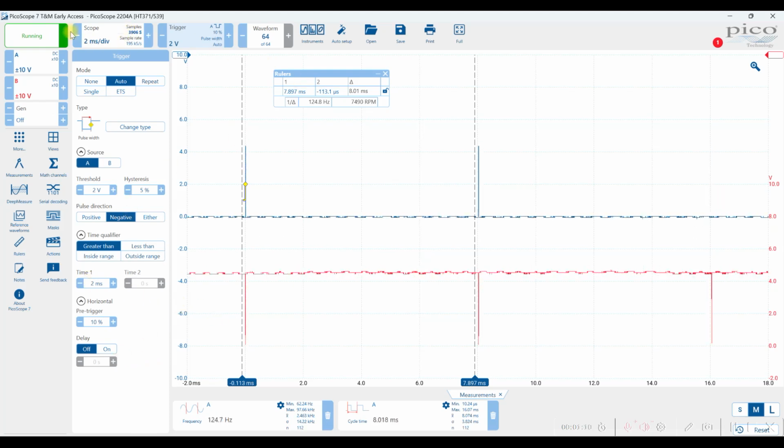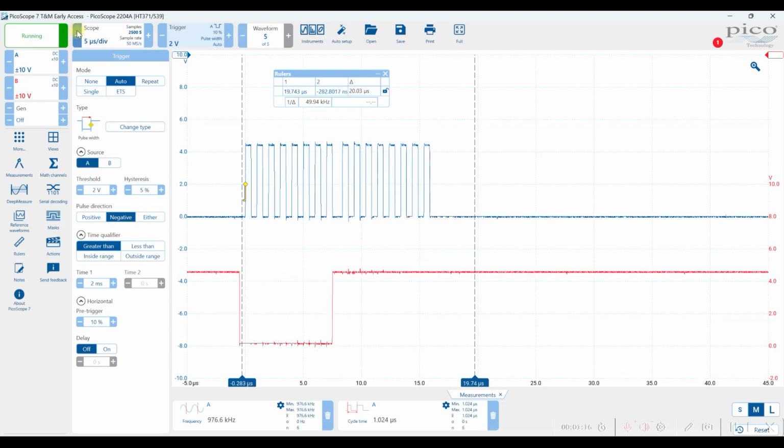Now I'm going to zoom in a little bit by changing this to a lower value. And now it seems to be a little bit more meaningful information. I have two sets of clocks, so number of bits here and a number of bits here. For my data, which I know is 0, 0, 0, and FF.